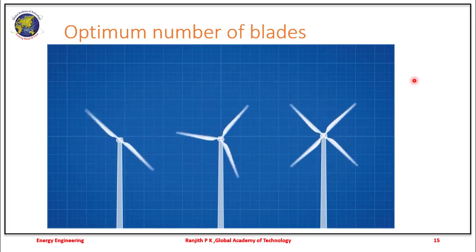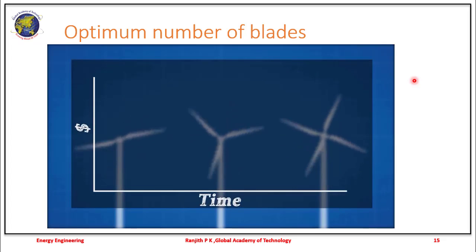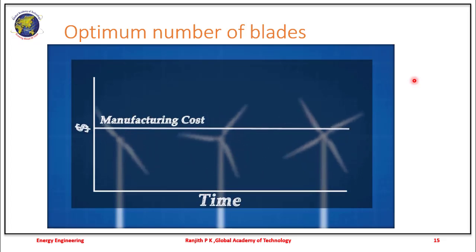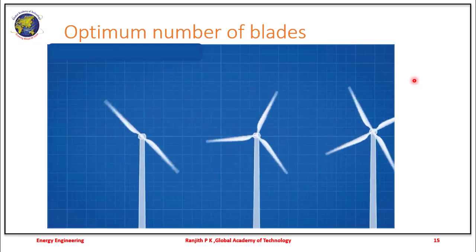We can easily eliminate the 4-blade design with a quick cost analysis. Each of these blades costs a lot of money. Adding a 4th blade provides such a marginal increase in performance that it does not justify the additional cost. So it's down to 2 and 3 blades.